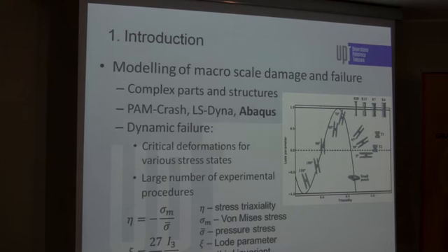And also we can have tensile specimens with various notches. The issue with this, especially when trying to find the parameters for advanced materials such as composites and polymers, is that the manufacturing of these would require special molds, and it would require high costs for production of molds and specimens.